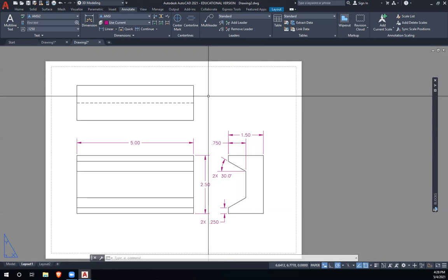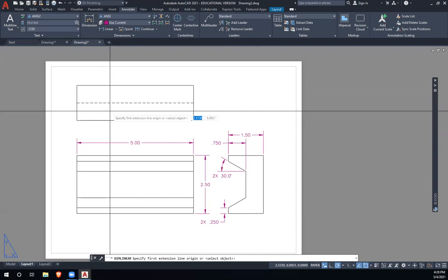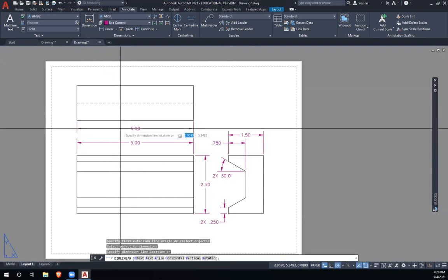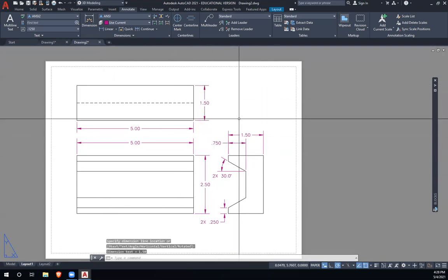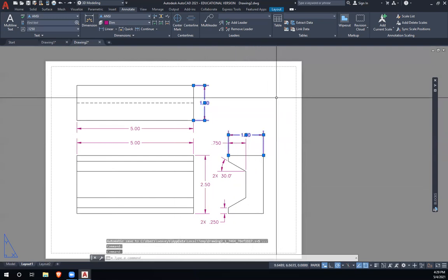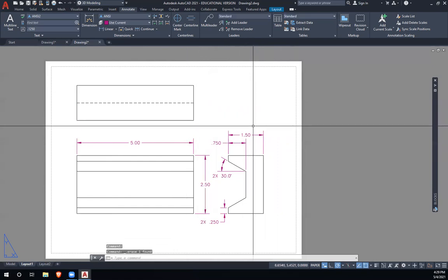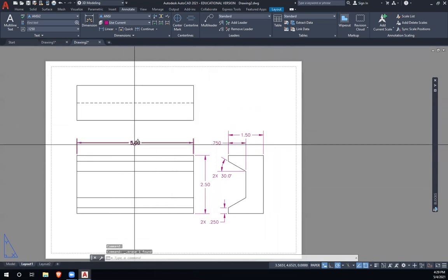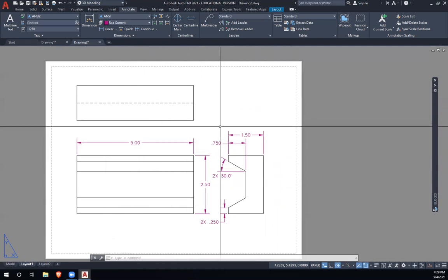Also, we don't want to duplicate dimensions, right? It's so easy to do because I have 3 views, and so I could dimension the length right here, right? And I could dimension the width right here. And oh, that looks so much better because I have so much stuff on there, right? Well, this dimension and this dimension are redundant, right? They're the same. So don't do more work than you have to, right? So I could have put that 5-inch dimension on the top view to keep it from being lonely, but still, that's more of a grouping thing too. So, all right.